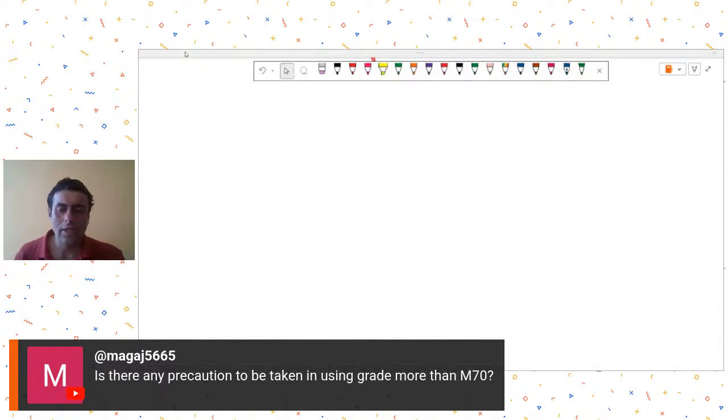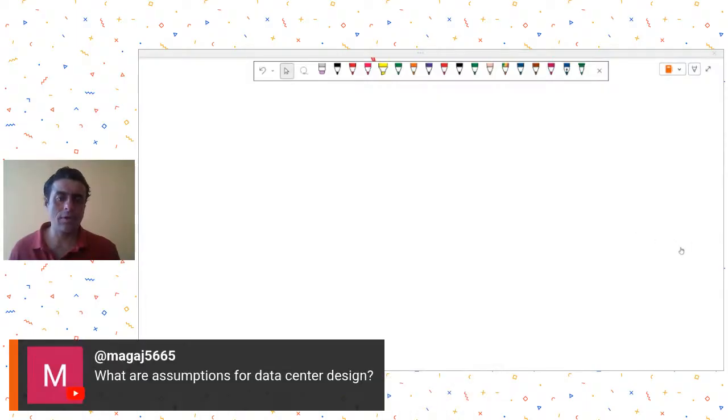Maybe if you are adding GGBS, because generally for higher grade concretes you have to add GGBS, you need to look at the crack control, because the heat of hydration I think will be more. So maybe you need to look into that. But other things I'm not very sure, because I have not worked on it.